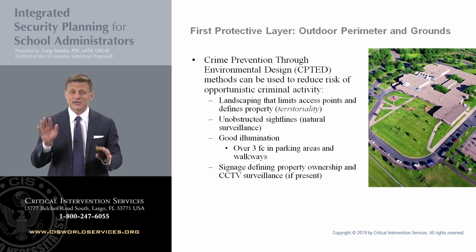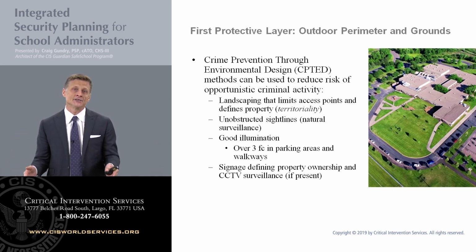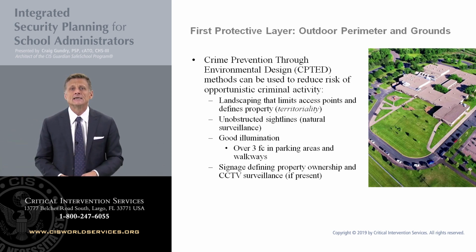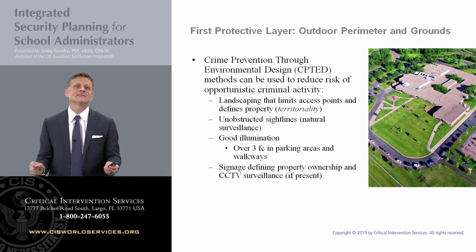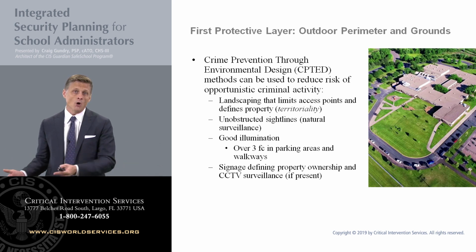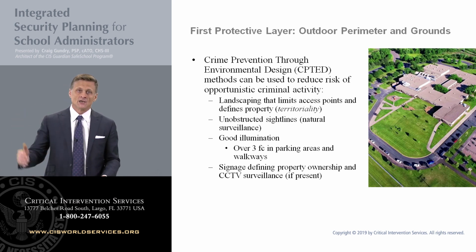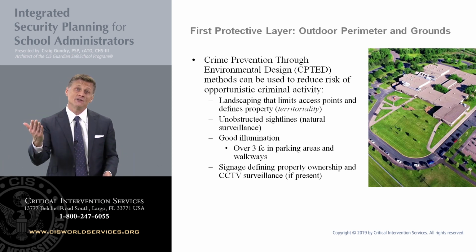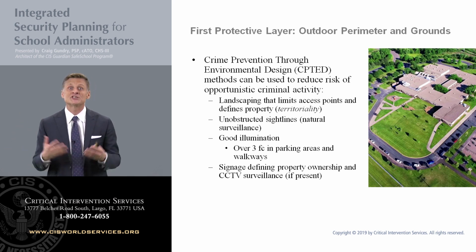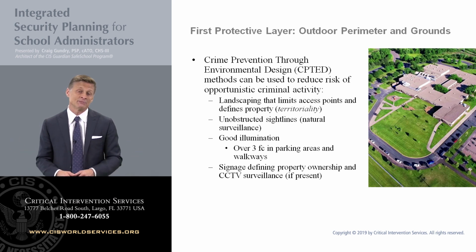The Illuminating Engineering Society has guidelines for illumination in different types of environments, like walkways, parking lots, as well as a lot of different types of indoor applications, parking garages, and things like this. Without getting overly detailed, I would at least recommend that most spaces where students and visitors to the campus are likely to walk, such as parking lots, walkways, areas between buildings, etc., are illuminated to at least a level of 3-foot candles or greater. That will at least provide adequate illumination for recognition of activity and subject identification, where the guideline is 2-foot candles, but then also improves the perception of safety in the environment for those students that happen to be outdoors at night.